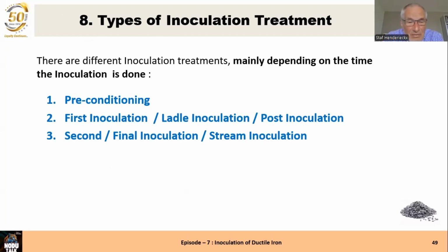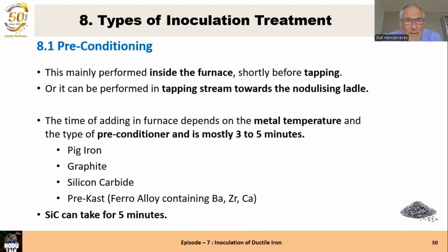Here again, there are 3 times where you inoculate, where the first, the preconditioning, is it an inoculation or not? In some literature, they say it's not an inoculation. In other literature, they say it is. Let's see what it is. Next slide. So the preconditioning is a material, an alloy, you put inside the furnace shortly before tapping. Or it can be in the tapping stream towards a nodulizing ladle, it can also be. But I prefer to do it in the furnace.